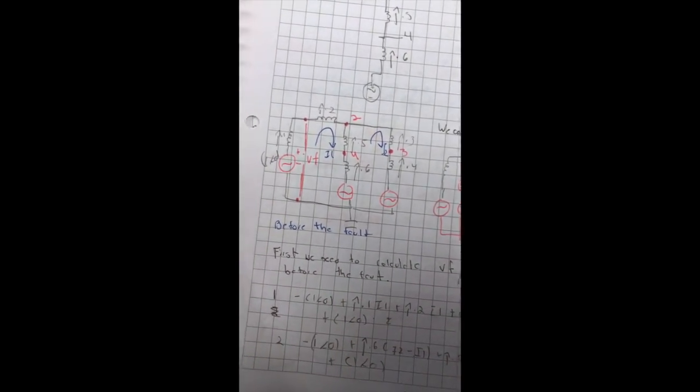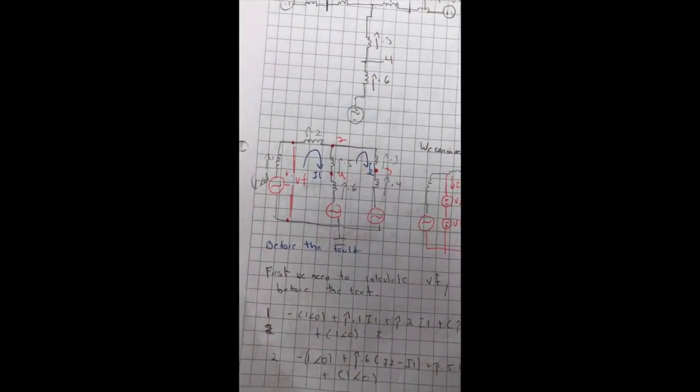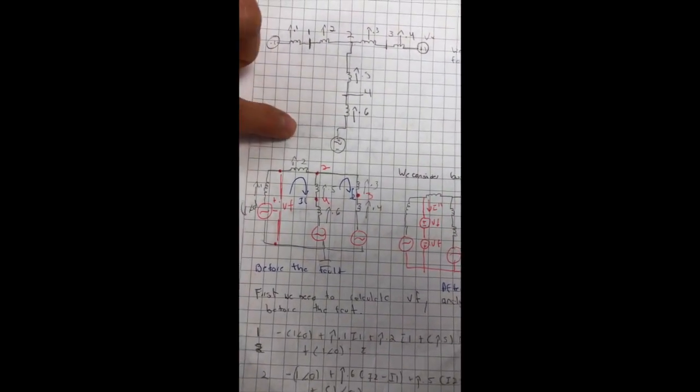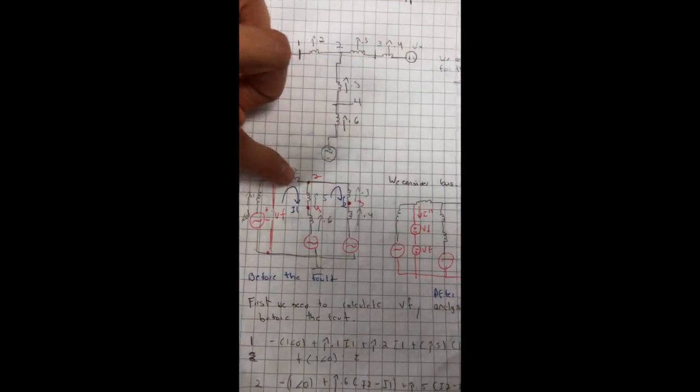Is this with the 3 generators? We assume for the voltage a value of 1 with an angle of 0. The impedances are 0.1, 0.2, 0.3, 0.4, 0.5 and 0.6 in per unit. Therefore, with mesh analysis, we did our meshes in the circuit, and we calculate I1 and I2 before the fault, and we obtained that the values of I2 and I1 are 0.